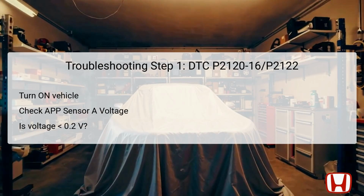Using a diagnostic tool, the APP sensor A voltage should be checked. If the reading is less than 0.2 volts, it indicates a duplicated failure and confirms the fault in the APP sensor or associated circuitry. This early stage in troubleshooting helps narrow down the focus to the sensor or connections, guiding further inspection procedures for resolution.